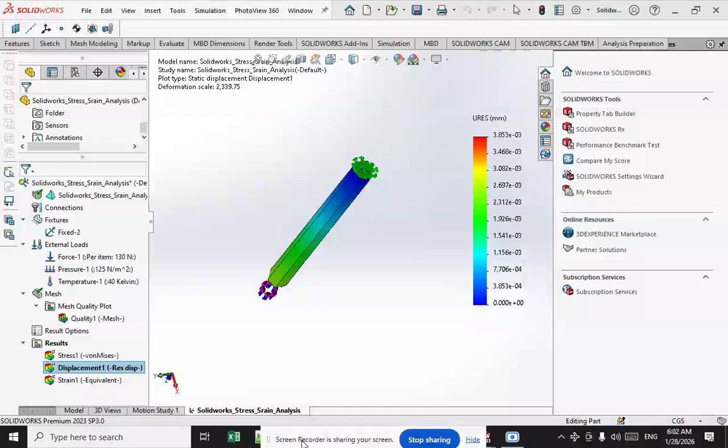However, the ratio of the allowable stress to the developed stress must be greater than 1 as a factor of safety. The design factor will be specified in the design requirements for the structure. All structures are designed to exceed the load those structures are expected to experience during their use. The design factor, a number greater than 1, represents the degree of uncertainty in the value of the loads, material strength, and the consequences of failure.